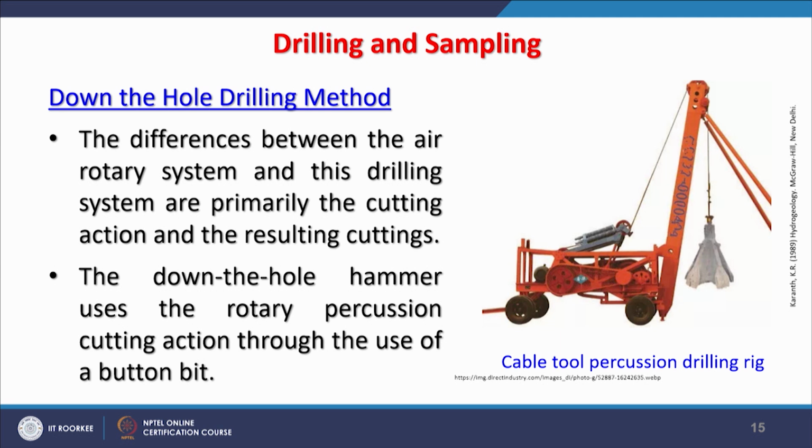One method will pulverize, meaning make powder of that material. So, assessing what kind of subsurface formations are there becomes a little difficult. But if through this method of drilling we get larger pieces of rock, then it is better. So, depending on what kind of groundwater conditions are there, accordingly we choose the different method.